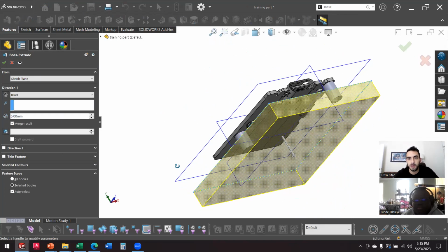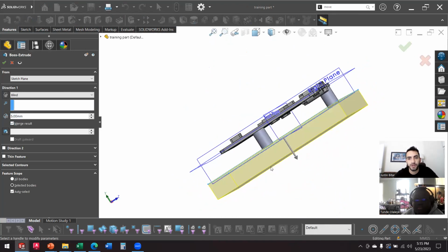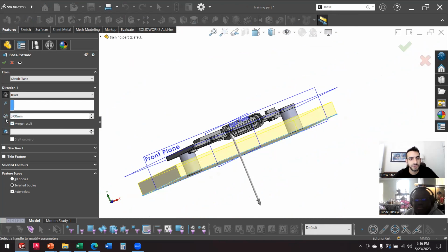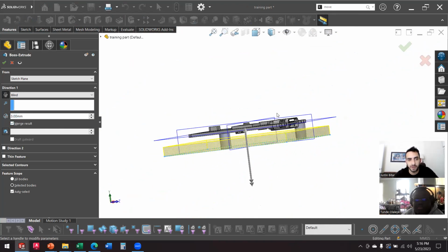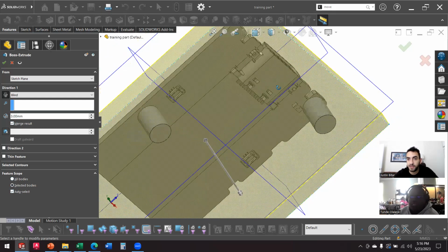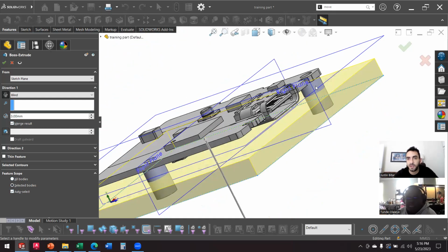And let's actually say, well, we want to get this base a little bit closer to this USB port, so we'll push it up through here. And we'll just say, yeah, like 3 millimeters, that's fine. Now we can merge the results, and it'll combine our base with the screw bosses, right?